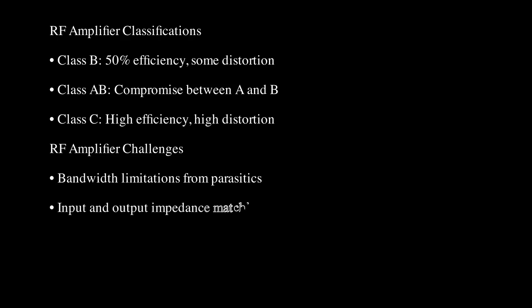Proper impedance matching is crucial for maximum power transfer and preventing reflections. This becomes more challenging at RF frequencies where component parasitics affect impedance values.